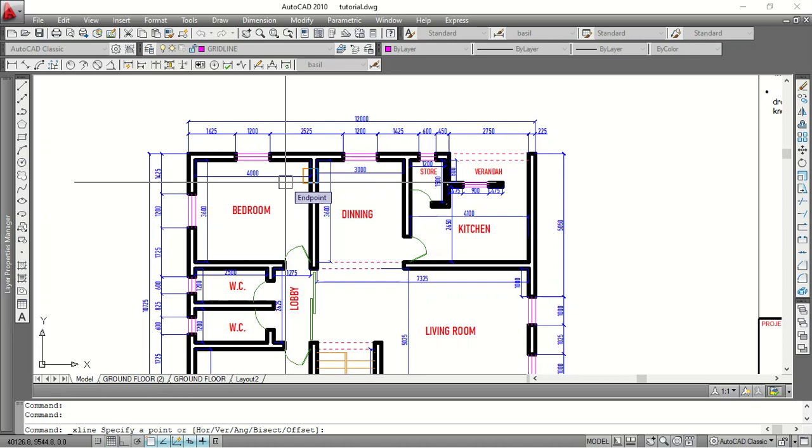Whatever wall thickness you're using, the dimension should flow from center to center. That's the requirement, irrespective of the wall thickness or whatever you're using for your design. Your line must always be center to center, so my grid is going to be running at the center of the walls.